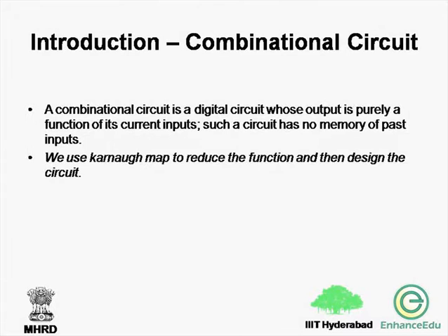Then minimize the number of logic gates in the circuit. This minimization can happen by algebraically manipulating the equations obtained for the output, or alternatively by using K-maps, that is, Karnaugh maps. Hence, step 5 is to draw the circuit diagram. With these steps, we can design a combinational circuit for any simple or complex problem description.